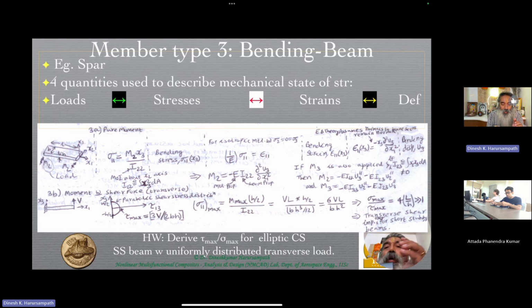So once again, you can either apply these moments on either end of a free beam, or you can clamp one end and apply it only at the other end. Then the clamp or support at the one end will cause the reaction of that particular moment. So it's a pure bending moment problem, pure bending as we call it.